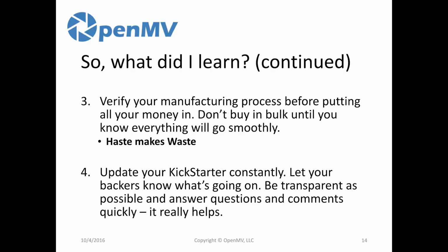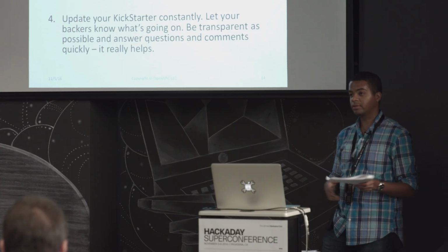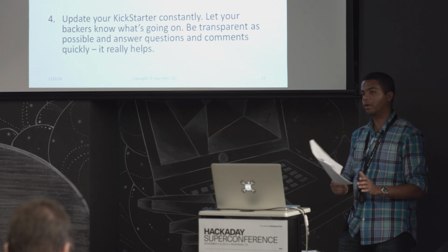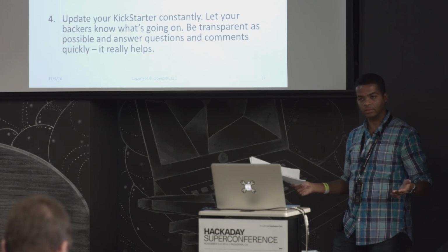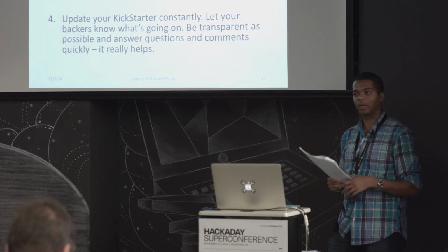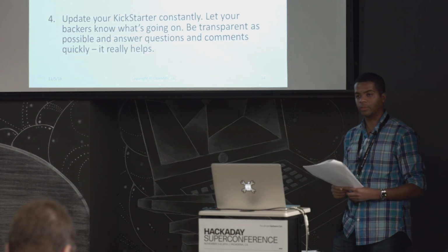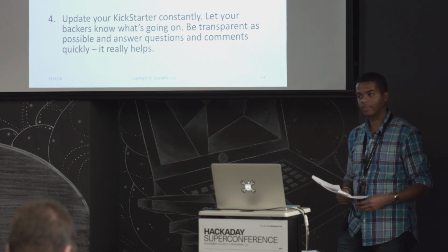Next slide. So verify your manufacturing process, and don't go out and buy a ton of parts immediately. One of the particular problems we had was we had all these extra camera sensors that we had to throw away pretty much. If we had just bought a small quantity and didn't spend thousands of dollars buying thousands of sensors, we would have learned about this particular problem immediately and not have blown so many PCBs and camera sensors on it.